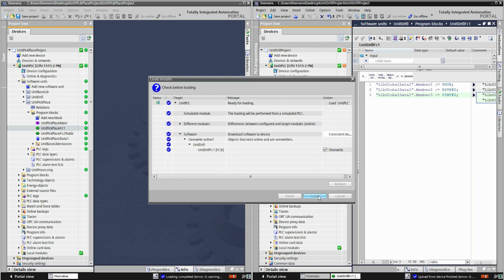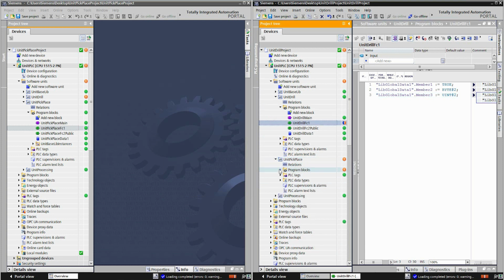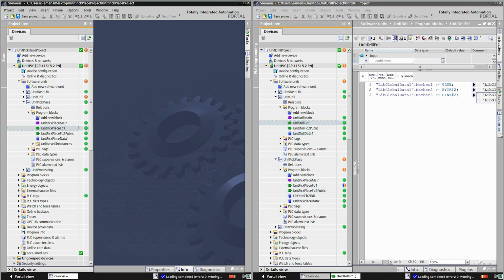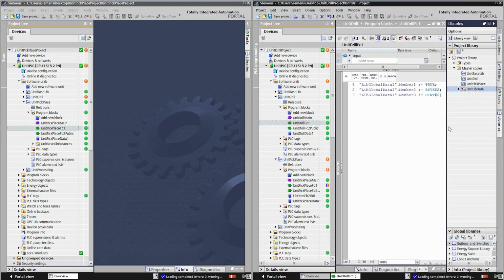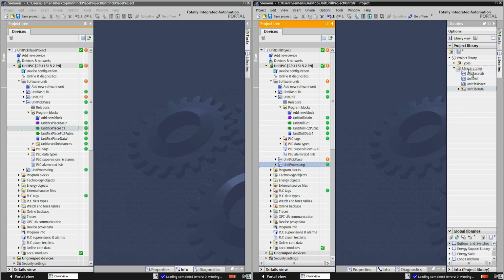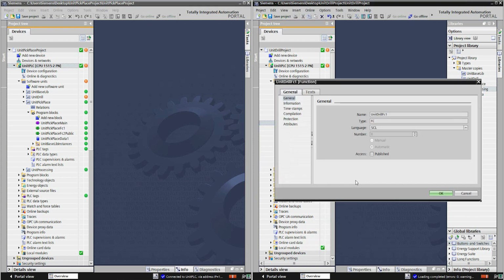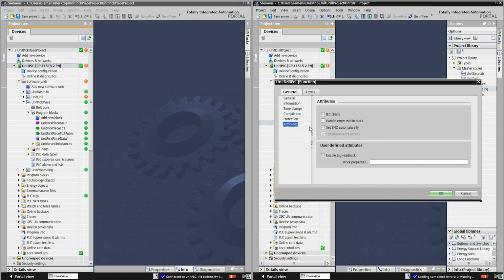At the end of the day, we recommend to completely synchronize at least one of the project copy with all the elements from the online PLC to archive and save a consistent project. In general, software units provide a smart way to structure, develop, protect and distribute entire program parts to your favor. For that, the TIA Portal library concept can be used. To reach the best runtime performance of the PLC and also to create a software architecture of tomorrow, software units are exclusively designed for optimized programming and symbolic addressing.